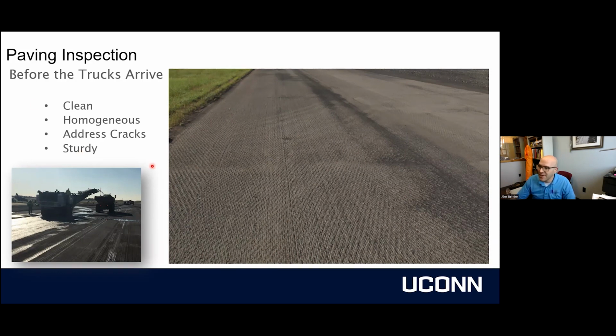And then finally, addressing cracks. Cracks are really important. I realize it's the third and not the fourth bullet, but I wanted to talk about that last. Addressing cracks is really important because a crack is an indicator that there's movement in that area. Movement in engineering terms is strain, but whether you call it movement or strain, it doesn't really matter. The more that the pavement structure itself is moving under loads, the sooner we're going to see cracks in our new layer. That's called reflective cracking.